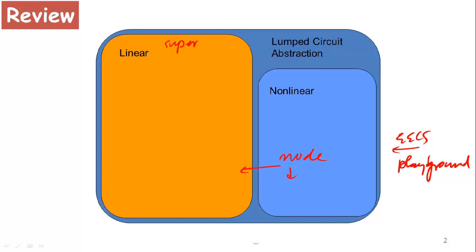circuits alone. We then looked at digital circuits, and it turns out that although the behavior of digital circuits is nonlinear overall, once you fix all the switch positions, digital circuits are composed of many switches and other components. If you fix all the switch settings, you are left with generally a linear subcircuit, at least according to the SR model of the MOSFET that we learned about.